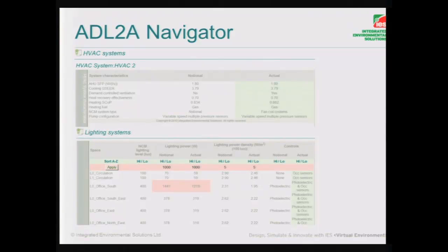And these are all outputs that the users can get as soon as they have any sort of geometry available. So really from the concept stages of the analysis, the architects can say, well, rather than using the criterion 2 U values as my specification, these U values here, these are really what I should be trying to hit, or perhaps even improve upon them. Okay.